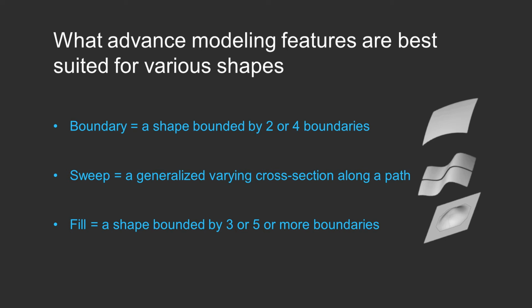I also believe that sweep is probably the highest quality surface you can get, because as the profile sweeps through the path, the cross sections are just higher quality because it avoids inflections, and you just get a much nicer result if you do things right.